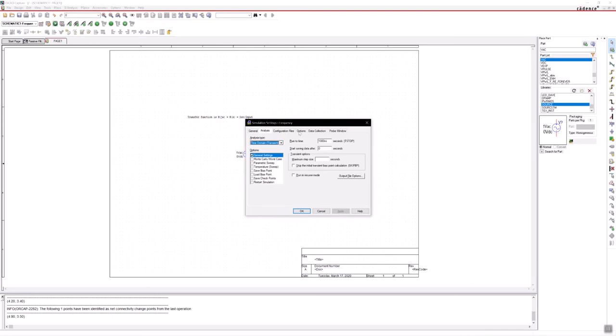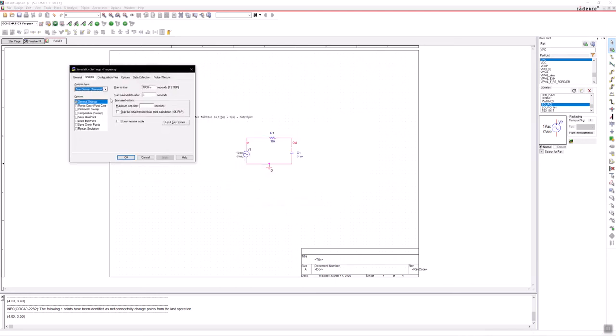So my settings have come up here, and I have to change what it is I'm doing. The analysis type here says time domain transient. If I pick it up here, there are 4 choices. The kind of obvious one, in my opinion, would be the AC sweep or noise, because we're again wanting to see how this thing is changing with frequency. So if I select AC sweep, I can see here now I've got an AC sweep.